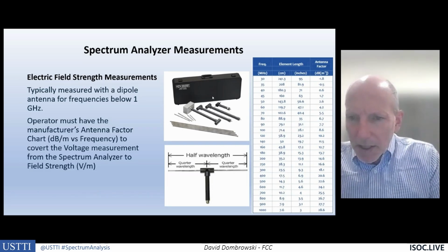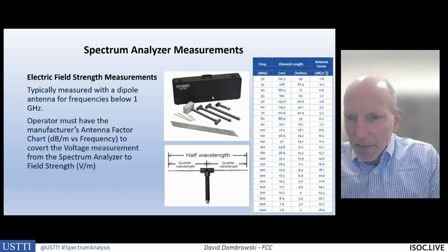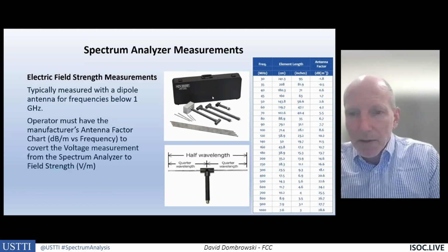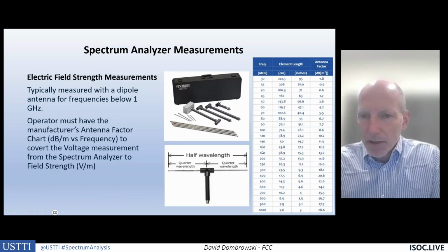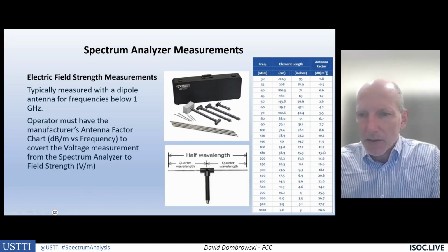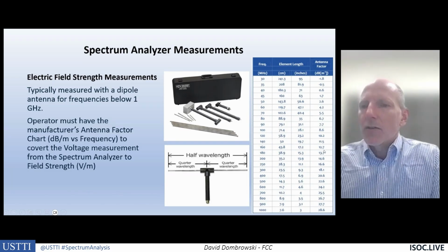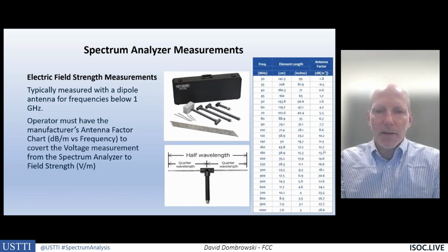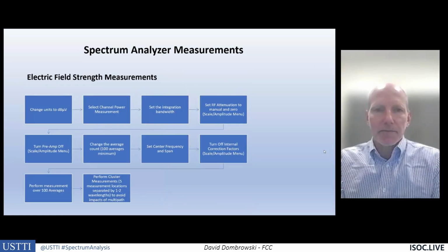So let's look between 160 and 180. You see the antenna factor is 12.7 and 13.7. If we wanted to know what the antenna factor is at 170, we just assume that it's linear and that it's right at the midpoint between, and that would be 12.7 plus half a dB. So that's 13.2. That's right here. It's 160 to 180, 12.7 to 13.7. Assuming it's linear, if we wanted to measure at 170, our antenna factor will be 13.2. So that's how you can determine the antenna factors for a specific frequency and measure the field strength.